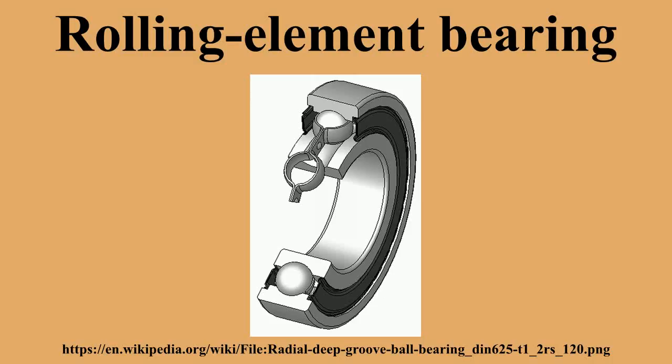The loads within a bearing assembly are also affected by the speed of operation. Rolling element bearings may spin over 100,000 revolutions per minute, and the principal load in such a bearing may be momentum rather than the applied load. Smaller rolling elements are lighter and thus have less momentum, but smaller elements also bend more sharply where they contact the race, causing them to fail more rapidly from fatigue.